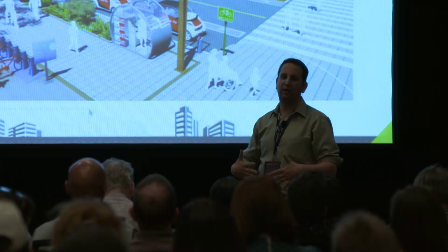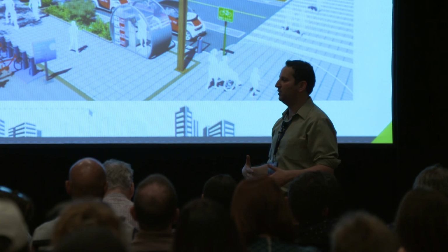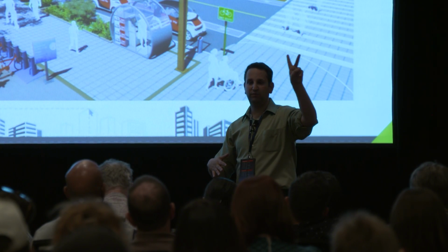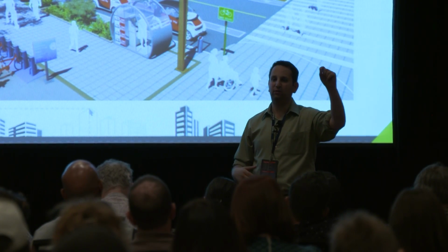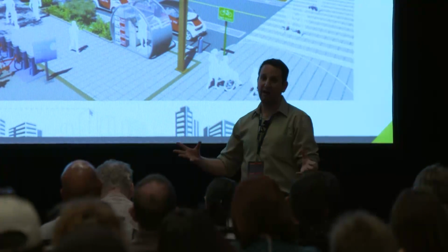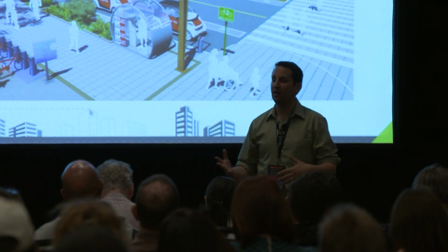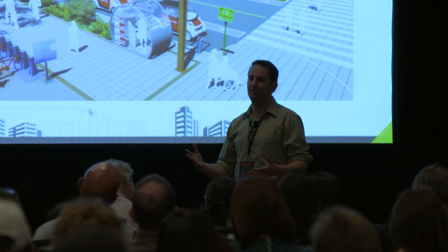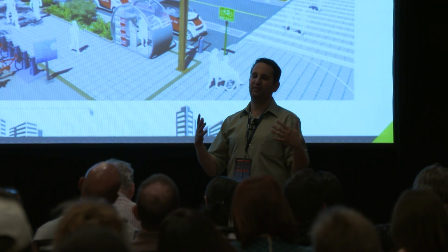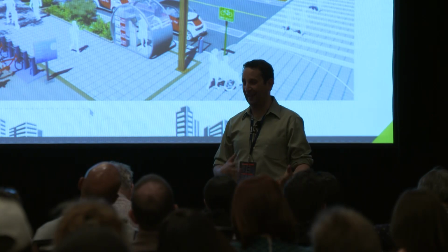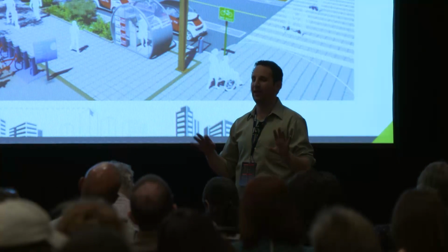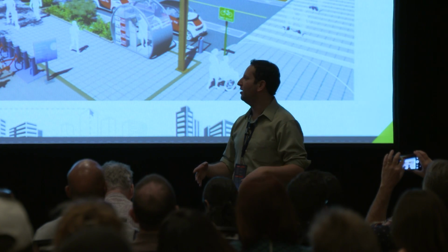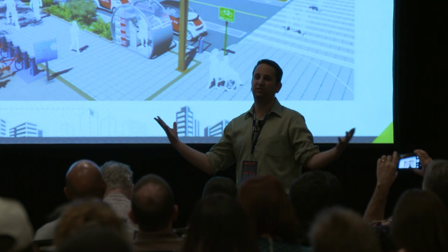SketchUp automatically compresses images to 1024 by 1024. You can turn that off. Our file size in SketchUp is composed of two things. Number one, the high resolution aerials will balloon the actual file size. Our typical file size is 100 to 200 megs. If you saw Spencer Branson's presentation, his file for the city of Fort Collins in SketchUp was 2 gigs. He sent that to me, and I was like, is there another way to open it? And then he blamed it on me because it was my method that I told him to use, which was totally fine because it was such a big aerial.